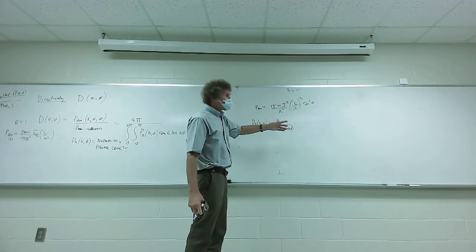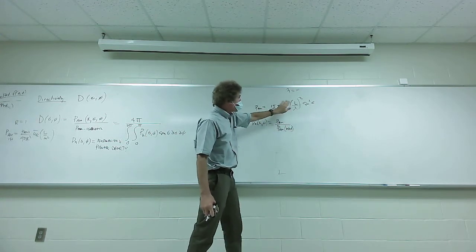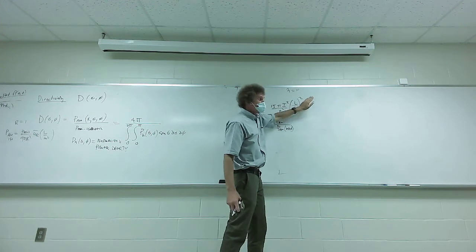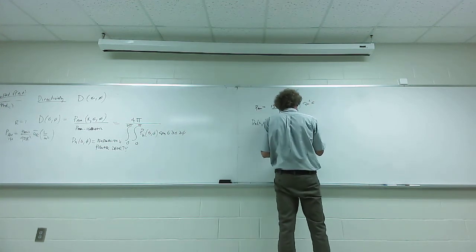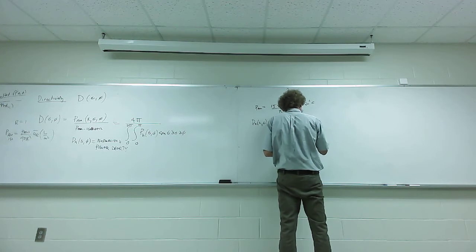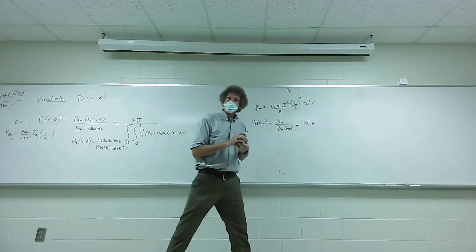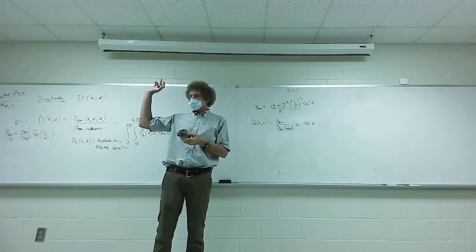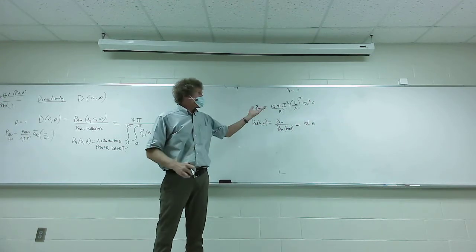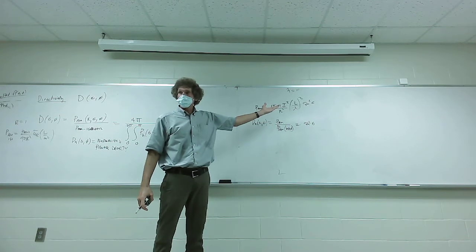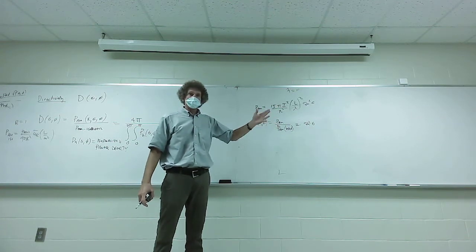What it's really saying is the maximum value is just that. If we divide it into this, we find that the normalized power density for this waveform is sine squared theta. Do y'all follow me? How many see that right there? Makes sense, normalization? Now, if that wasn't a sine, if it was cosine squared, then what would the normalized power density be?